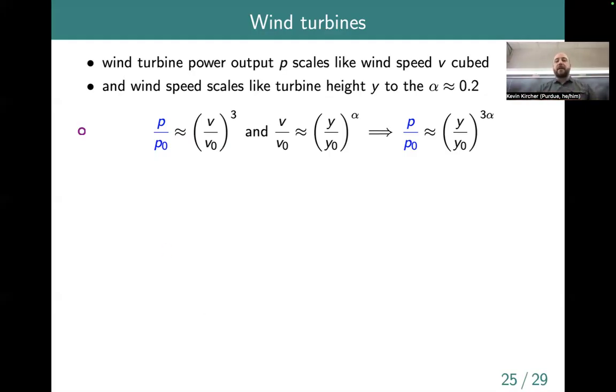So anyway, I'll talk very briefly about modeling wind and some of the considerations that come up there. Okay, so the power output, call it P, from a wind turbine basically scales like the cube of wind speed. And this is actually similar. We talked about pump and fan affinity laws, where the power consumption of a pump or a fan goes like the cube of the speed of whatever fluid it's pushing. It's basically the same math and the same physics, but run in reverse for a wind turbine.